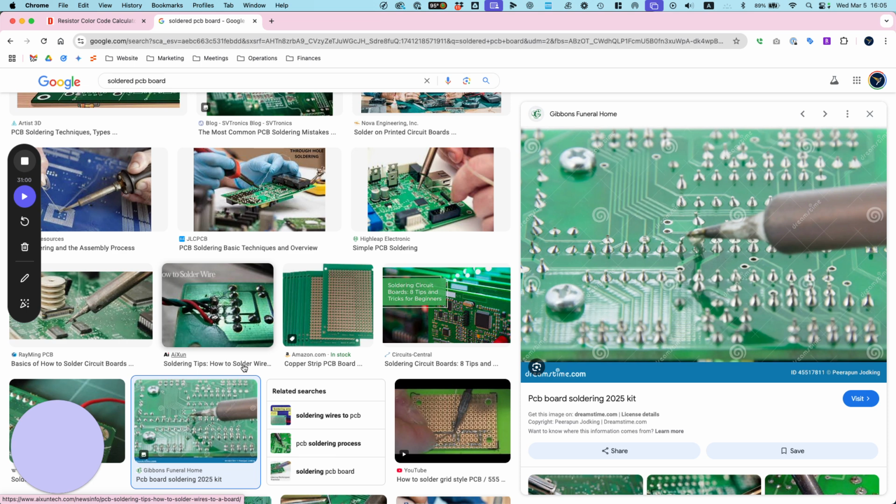But if the switch is open in your circuit, there's zero current, right? There's no flow. But there's still potential. Just like our 9-volt batteries sitting right here, there's still 9 volts, but there's no flow. There's no current right now. So voltage will exist even in an open circuit. So that means you can measure across, right? If something's broken, you can still measure across, you can still measure the circuit. Whereas with current, you have to be in it.